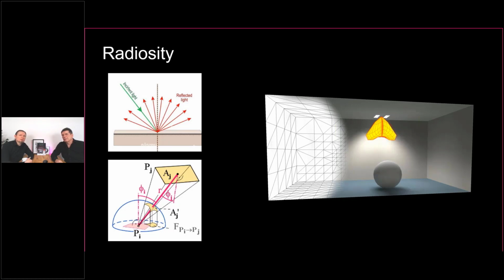If you just hit the calculation button in RELUX, you will end up with a radiosity calculation. And this calculation method is perfect for calculations according to standards. So if you want standard values for illuminance, uniformity, and so on, this is the method. It is a good balance between performance, accuracy, and visualization.